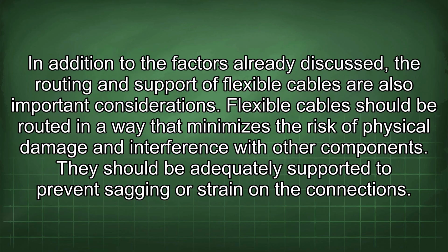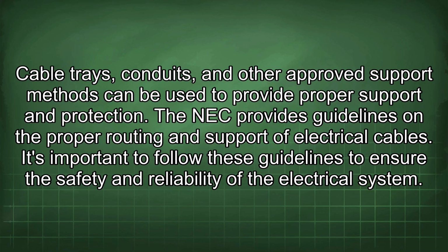In addition to the factors already discussed, the routing and support of flexible cables are also important considerations. Flexible cables should be routed in a way that minimizes the risk of physical damage and interference with other components. They should be adequately supported to prevent sagging or strain on the connections. Cable trays, conduits, and other approved support methods can be used to provide proper support and protection. The NEC provides guidelines on the proper routing and support of electrical cables. It's important to follow these guidelines to ensure the safety and reliability of the electrical system.